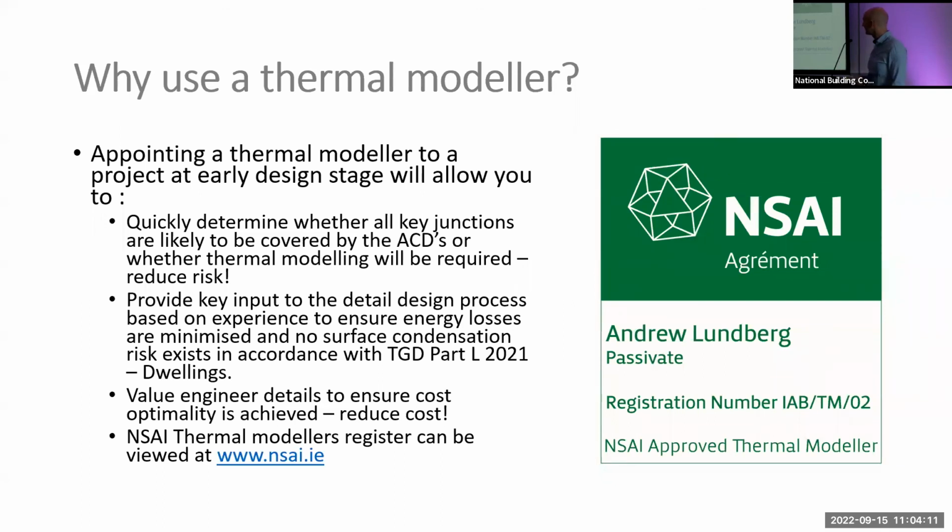Provide key input to the detailed design process based on experience, and to ensure that energy losses are minimized and no surface condensation risk exists in dwellings in accordance with TGD L 2021. Value engineer details to ensure cost optimality is achieved. So we are required to carry out design and construction in a cost optimal way. That doesn't happen on a per project basis. It's basically built into the performance values that we have.